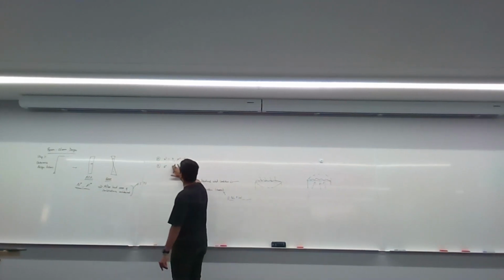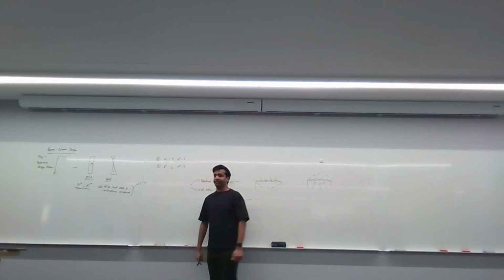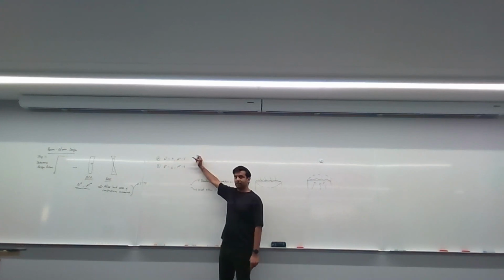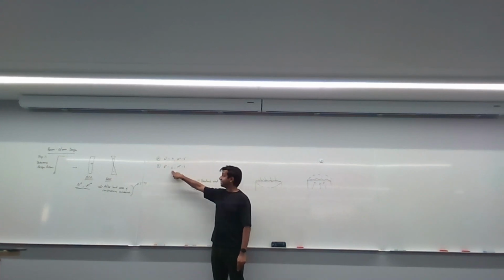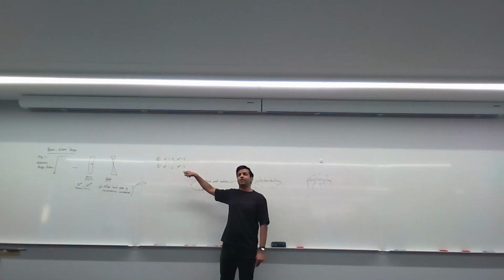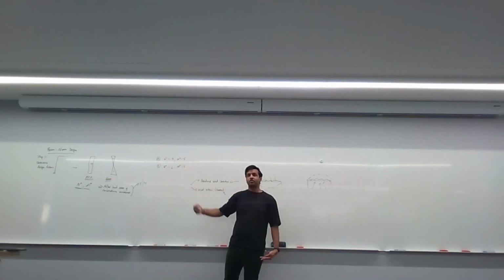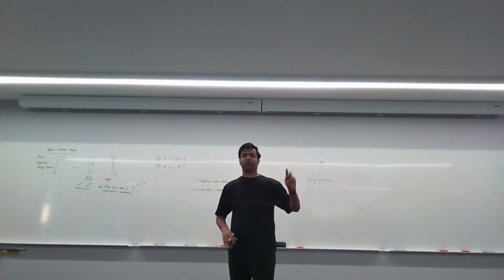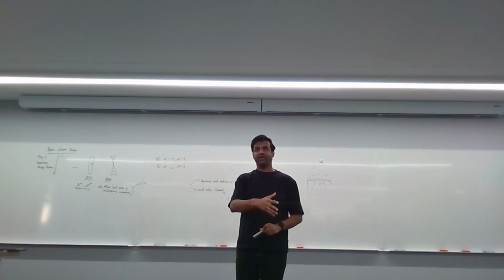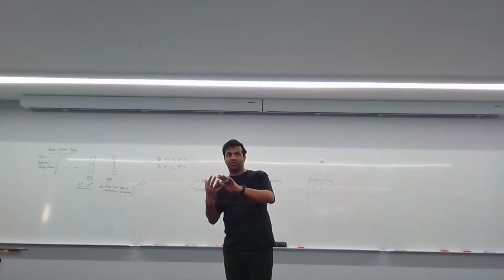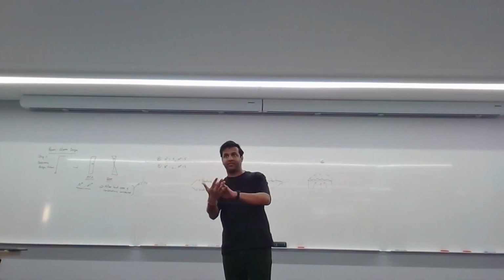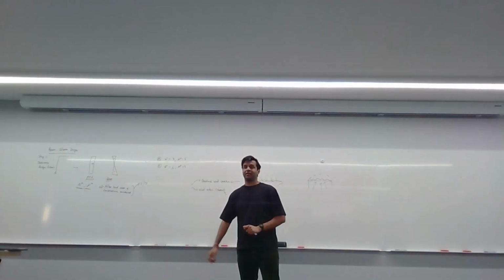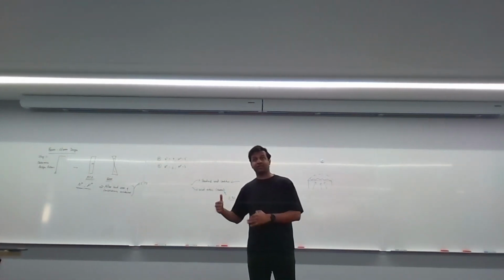But let's say, for example, this is what I have. Load combination A gives me 4 for N star and 5 for M star. Load combination B gives me 6 for N star, but 3 for M star. I wouldn't know which one to use, right? So you would have to test both. You do load combination A, and when it comes to your calculation where you're comparing your capacity and the actual design action, you would need to try both. That's a sneaky way to get you, but remember that's the concept behind it, okay?